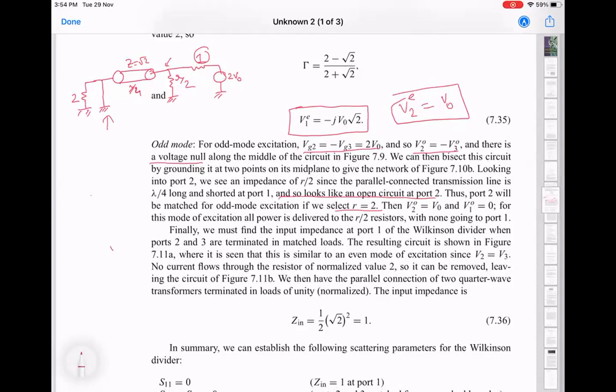Just like all such microwave circuits which use impedance transformers or any other transformers, there will be frequency dependence, and many things will not work. There are so many things which could go wrong. Matching could go wrong, isolation could go wrong, the division ratio could go wrong, the division phase shift could go wrong, and all of these will go wrong to different extents. So you again will define some reasonable range of operation which is acceptable for your application. But right now we are assuming everything is ideal. Otherwise, you cannot do this kind of calculation using the most general case.